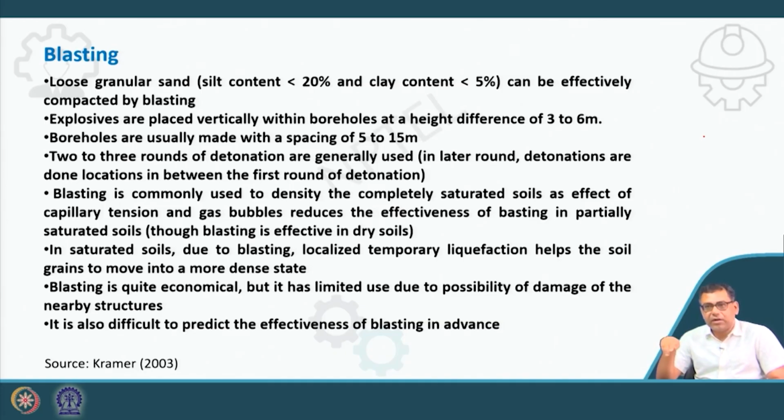So this is also done in a grid. These boreholes are usually made at a spacing of 5 to 15 meters. With this grid spacing, 2 to 3 rounds of detonation are generally used. That means first we do a round of detonation with a certain spacing in the grid pattern. Then in the later round, the detonations are done at locations in between the first round of detonation.